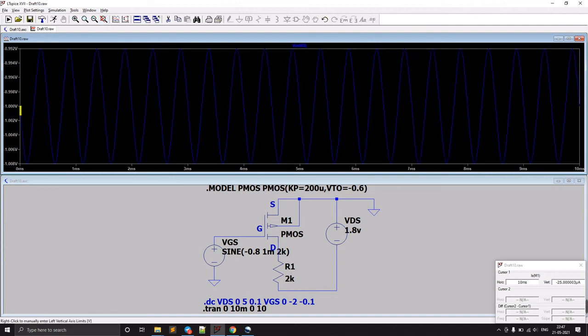This is from 1 volt, so 992 millivolt to something around 1 volt. So yes, this is the amplified version, because we can see 992 milli to 1. This has a swing of around 8 millivolt. Hence we can say this is an amplifier. It's amplifying, but the gain is very less. I think you understood these things. Thank you.